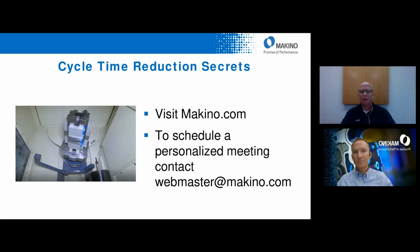Well, I mean, that depends. It depends on how large your part is. It could be some type of large housing that takes up most of the work zone. And then certainly, starting with features closest to the ATC and kind of working your way around if you can, you're going to see the benefit of that. But if it's a smaller part, then you may not realize such a savings trying to do that.